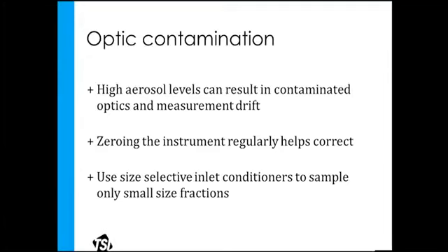The contamination: really high concentrations of aerosol inside those chambers can get kind of plugged up. So we'll address this by zeroing the instrument every time we use it. We go out every morning and we put a zero filter on, or a HEPA filter. Basically tell the instrument, hey, it should be completely dark right now, there's no light being scattered because I have a filter on it and there's no dust coming in. So anything that's contaminated the optics that's sending some signal right now, just ignore that part and just look at stuff that's above that when I take the filter off. So that's how we address optics contamination.